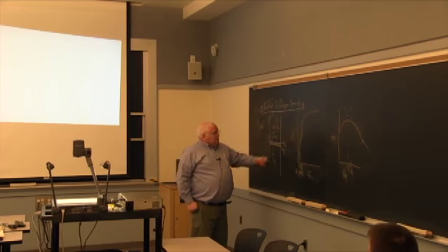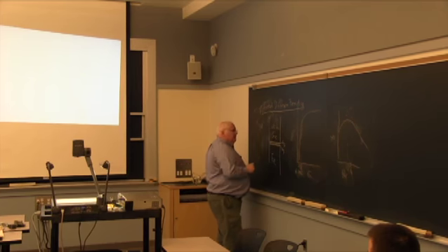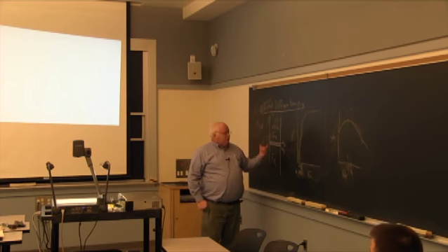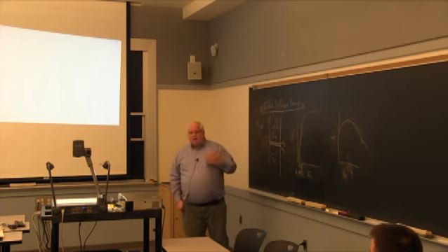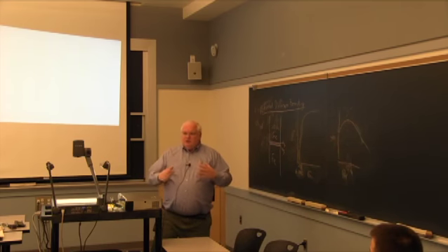Essentially you do this, and if you have a thin enough joint, and this could be on the order of 1/1000th of an inch thick, you can actually get a joint that has a strength in tension of 100 KSI. Well, how do you get that? Well, it's called contact strengthening, and I'll talk about that later. But in very thin joints, the material enters a state of triaxiality when you pull on it.